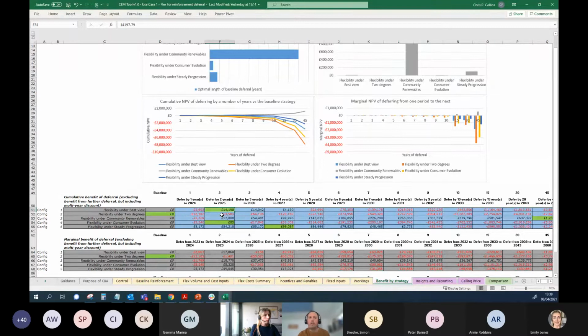And in a low growth scenario, that's likely to be the way of things, because when you've only just had a small exceedance, the amount of flexibility you need to procure tends to be quite small. But as load continues to grow, the exceedance on a substation grows correspondingly, and you need to procure more flexibility to keep your peak load in check. So that cost of flexibility tends to go up if the load is growing. So there tends to be a point at which it no longer makes sense to carry on procuring flexibility.